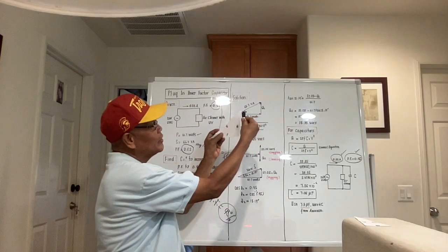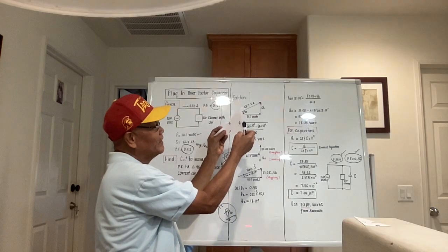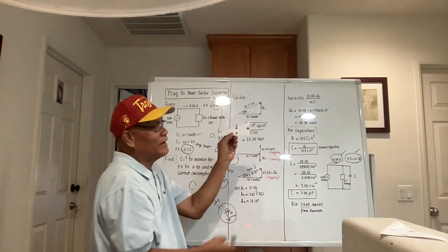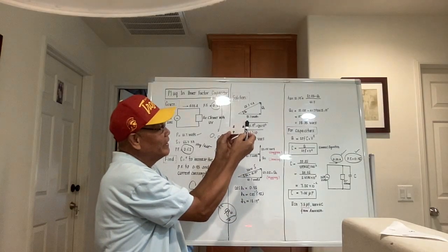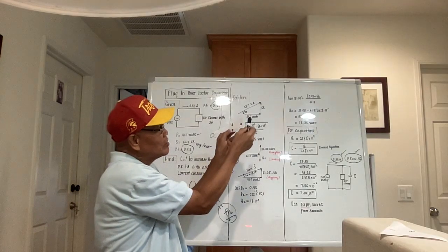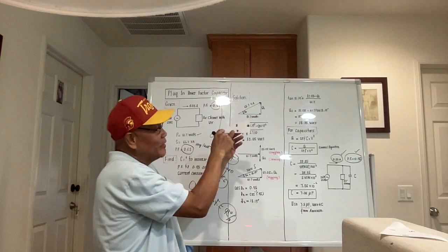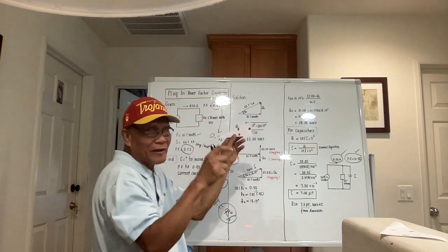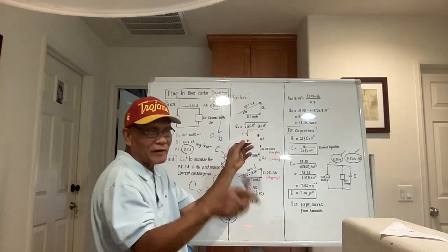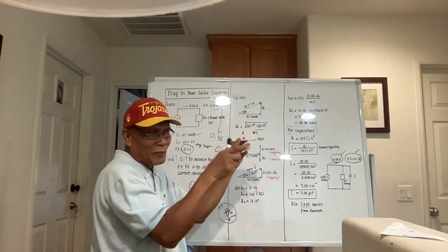If this is the original Q, you try to lessen the Q up to this height here. So what will come out will be this triangle here. So it becomes smaller already. This one remains the same. So if this becomes smaller, what will come out on the hypotenuse will be smaller. And if the hypotenuse is smaller, which actually represents the total apparent power that is needed in the computation of the total current, if this is less than the original, of course the current will be less.